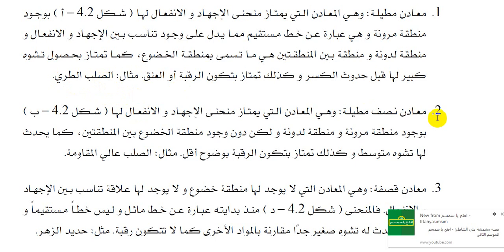As I indicated, God willing, for the semi-ductile materials, or semi-ductile metals, the metals with a stress-strain curve illustrated in figure 4.2b are characterized by an elastic region as well as a plastic region, but without a yield region in between.